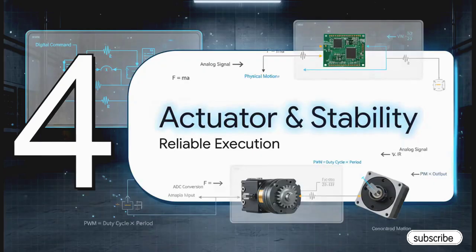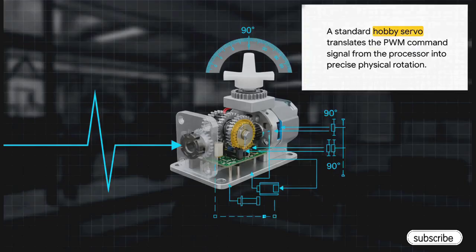All right, that brings us to the output stage. Actuator drive and stability. This is where the rubber meets the road, so to speak. It's where our digital command finally becomes physical motion. And let me tell you, this is where solid electrical engineering principles become absolutely critical for reliable operation. So, the actuator in our system is a standard hobby servo. Its job is really simple but important. It just listens for that PWM signal from the processor, and then it translates the length of that pulse into a very precise angle, physically carrying out what the operator wanted in the first place.